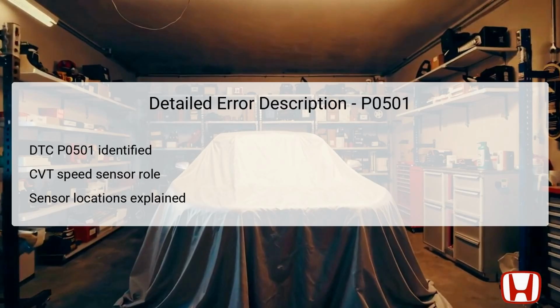The DTC P0501 indicates a malfunction in the CVT speed sensor circuit. The CVT speed sensor is responsible for monitoring the rotational speed of the transmission's fluid and providing this data to the TCM for optimal performance. A key aspect of its function is to maintain a precise relationship with the CVT drive pulley speed sensor to ensure that gear transitions are smooth and efficient.